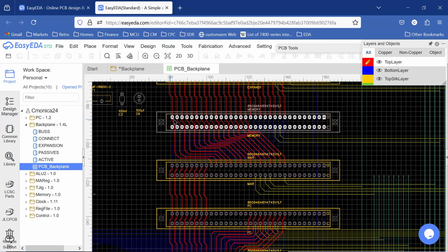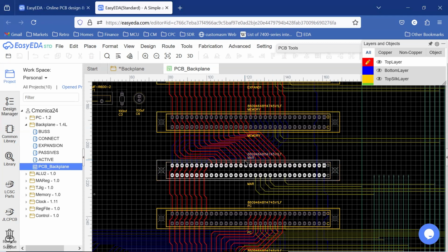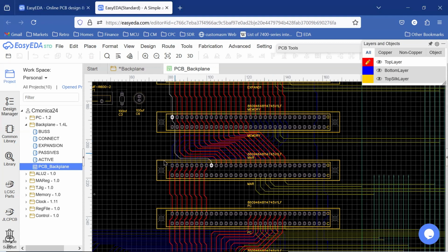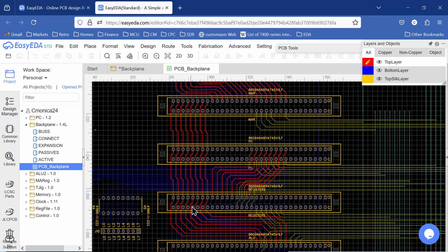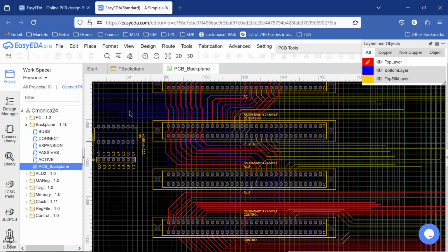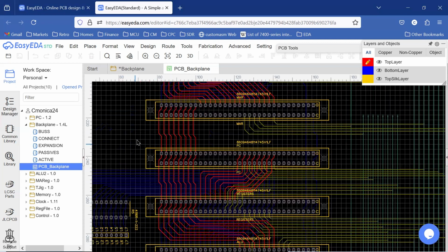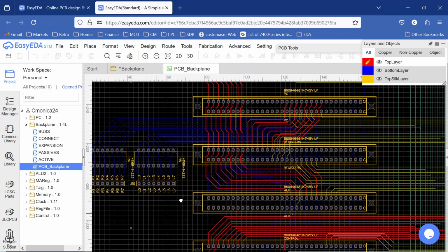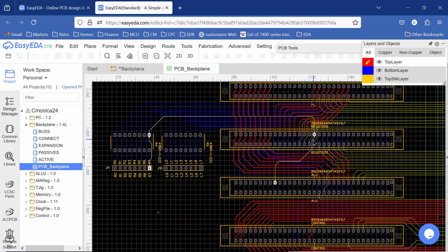So you can see here we bring in the address lines. These are coming over, and then on the bottom we can see that our data bus lines are flipping over to the other side. But you can see that we're mainly carrying our data bus lines through on all the cards and threading them down, and the same thing for the left and the right buses. So we have a left bus here coming down, and then we have our registers card, which is really where we have left and right bus come out of that card, and they are coming into the ALU, right?